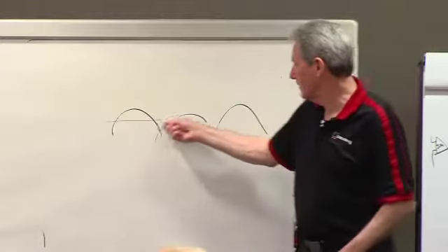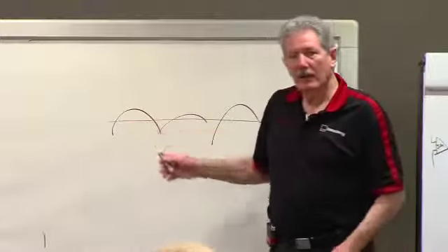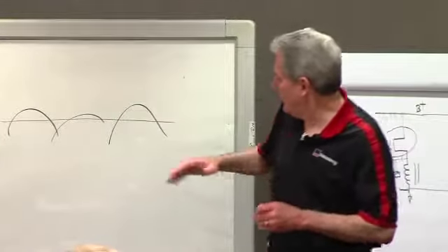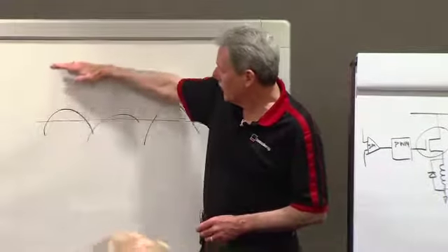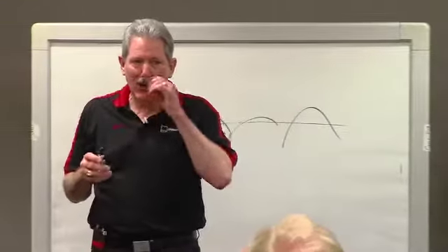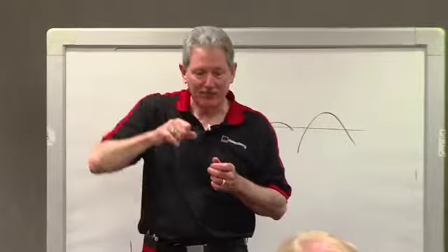Remember I told you how the regulator turned on and turned off? According to this, here's your set point. That's not the smartest way to do it, because with load, this will increase. So your load regulation deteriorates on a bang-bang regulator.